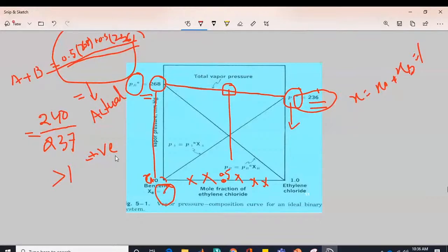Actually, the type of condenser comes from the inventor or from the company, how they manufacture it. It totally depends on the surface area they are going to provide, and the contact time they are going to provide for the vapor with that cooled liquid. The more they are in contact, the higher the heat transfer. You remember that, right?